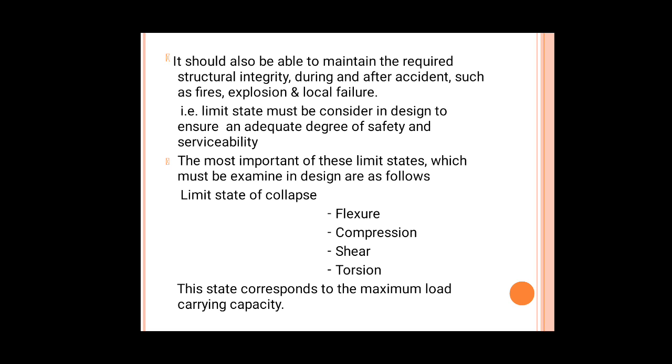It should also maintain the required structural integrity during and after accidents such as fire, local failure, explosions, etc. That is, limit states must be considered in design to ensure an adequate degree of safety and serviceability. The most important limit states to be examined in design are flexure, compression, shear and torsion.